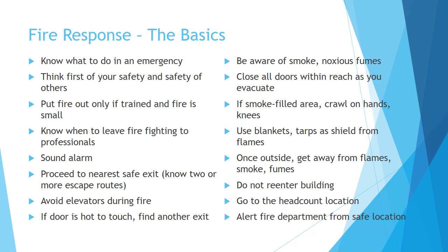Use blankets and tarps as shields from flames. Once outside, get away from the flames, smoke, and fumes. Do not re-enter the building. Go to the head count location and alert the fire department from a safe location.